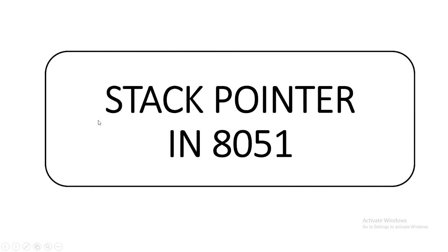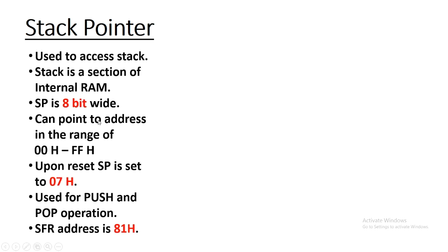Today we will learn stack pointer in 8051. 8051 has an 8-bit stack pointer, SP. The stack is a section of RAM. So if there is a section of RAM which is known as stack, there must be a register inside the CPU to point to it. And that's why stack pointer is used.